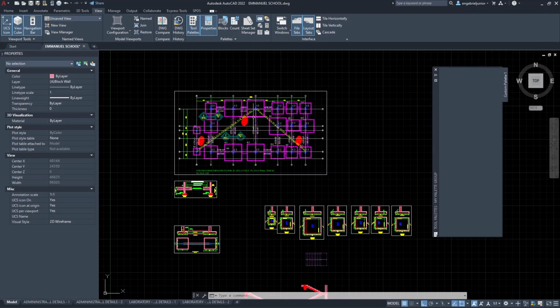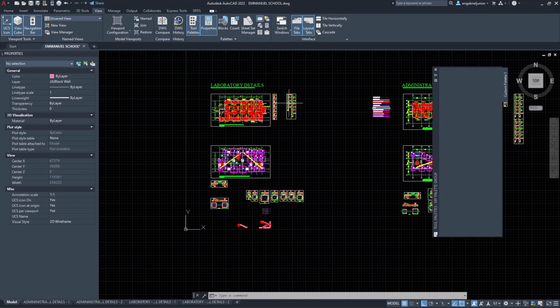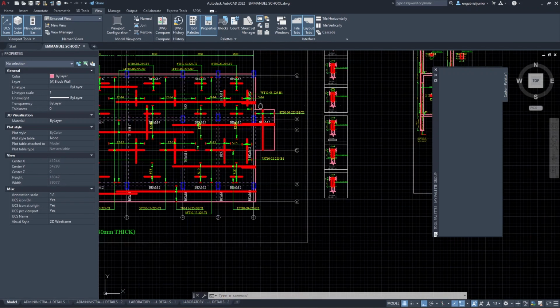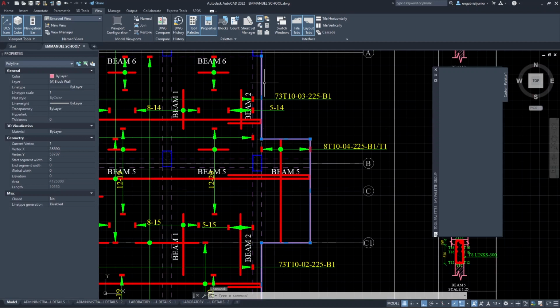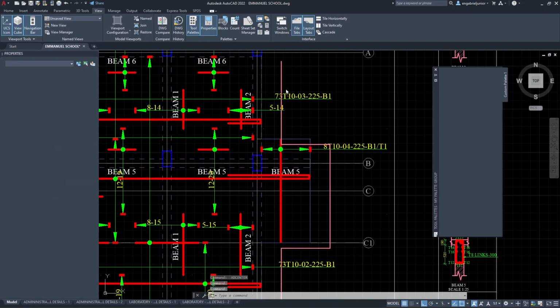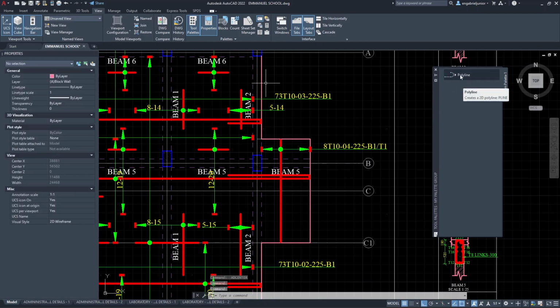Now, for example, we're in this drawing. Perhaps I want to add some lines which I'll be using frequently. For example, I wish to add the slab line, so that I don't have to keep on selecting the polyline tool and trying to select the layer I'll be in. I'm just going to use it directly. So I select it, right click and hold, then drag it into the palette. Immediately when I leave it, it's going to place it there.